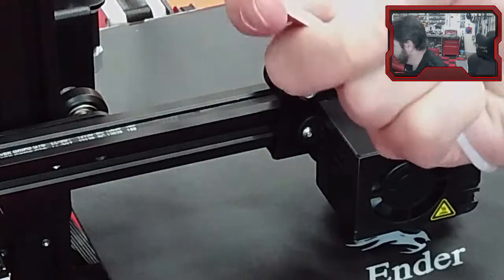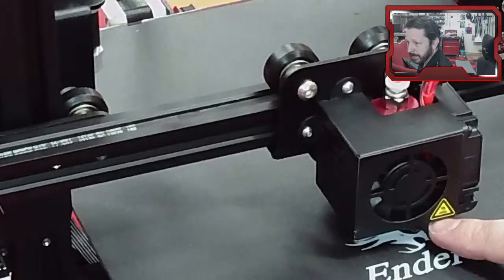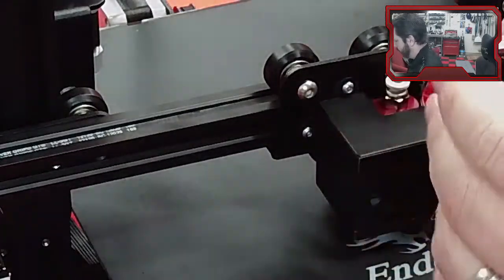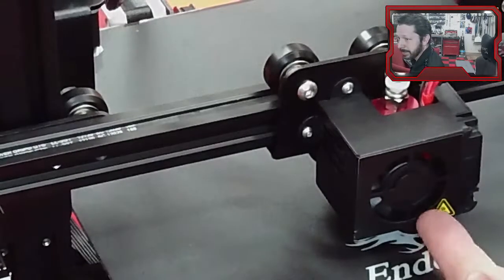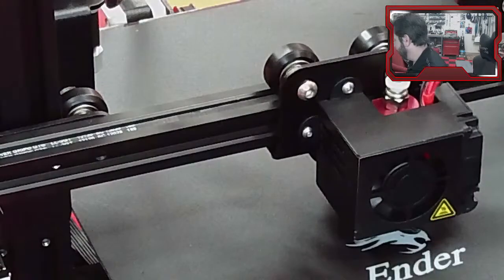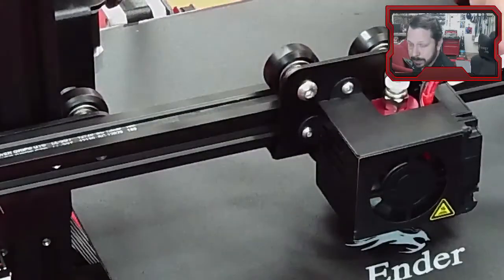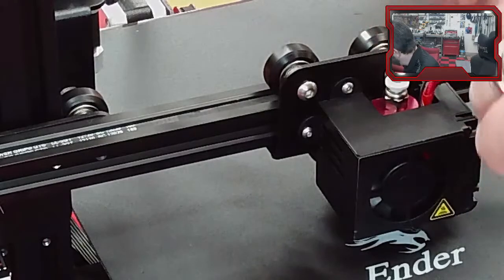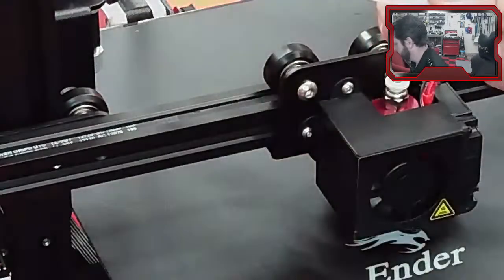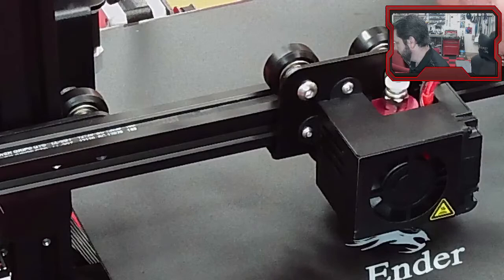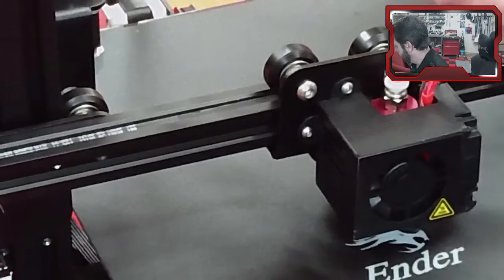There's definitely been worse, but that little bit of an angle, what can happen is the filament comes out here. At this point, it's basically in the hot end and it's molten, and it can come out between that angle and the seat inside the hot end, so the top of the nozzle. And then it's outside of your path at that point. It's not in the tube, it's not in the nozzle, it's outside, and it will create clogs. So I'm going to leave it like it is for now because I don't have the tool already out to chop this off straight. But check yours and make sure that it's as straight as possible across this tube. And it's not at an angle.